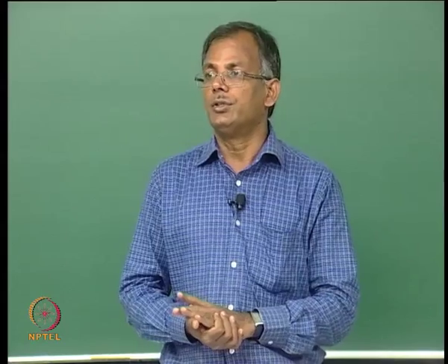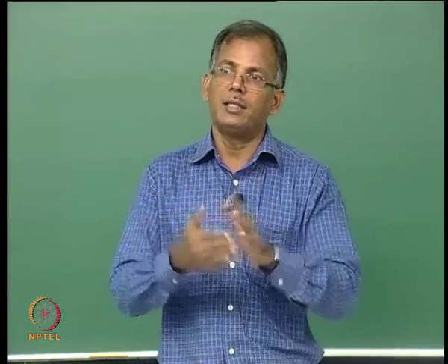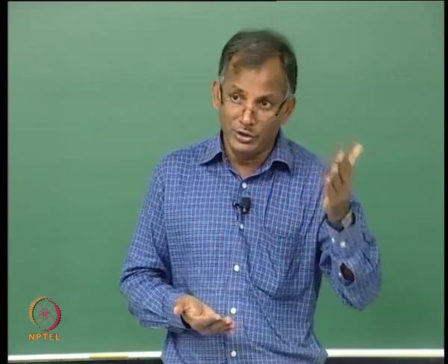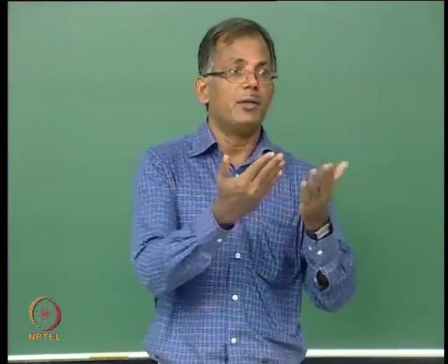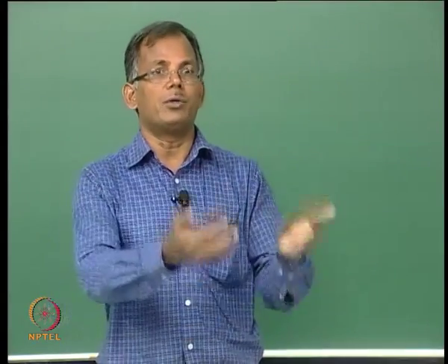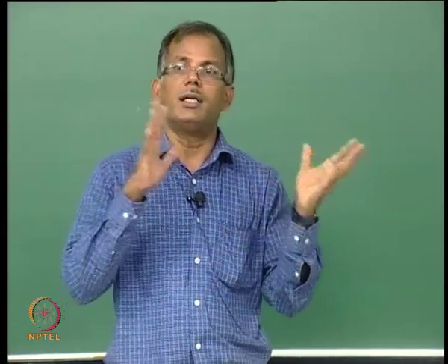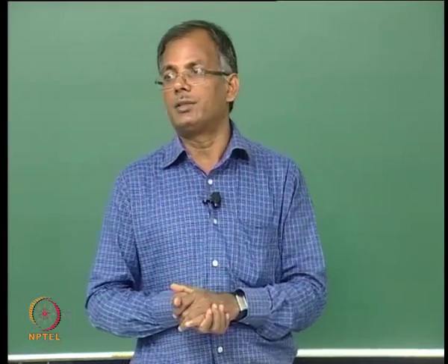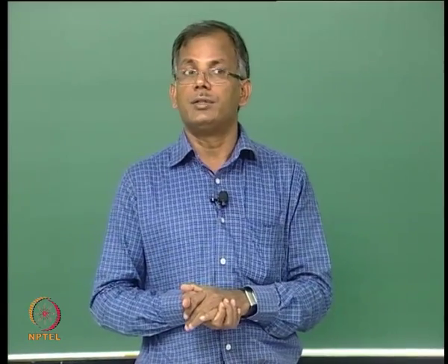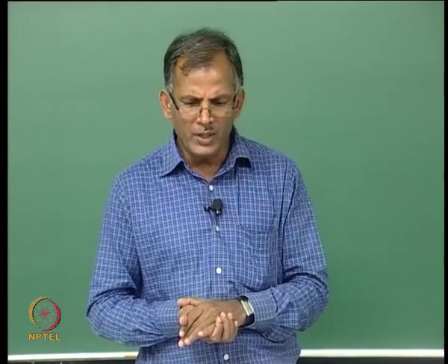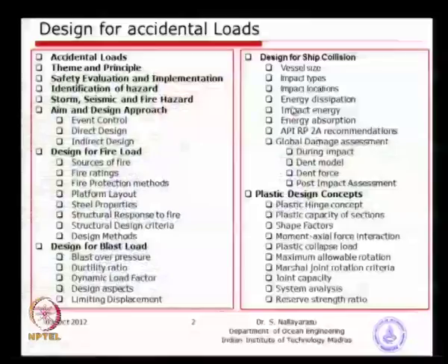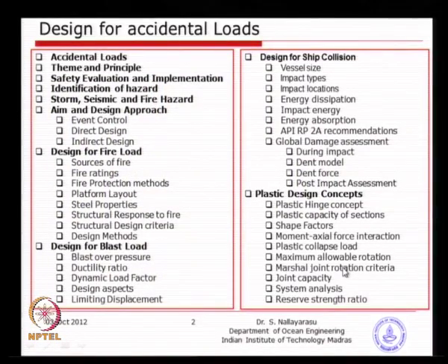So, those things may happen, and in those cases the structure may get damaged, and you may have to repair it in the future to bring it back to service, but it is not necessary that it should collapse. So, you need to have redundancy in the system, so that the structure has sufficient reserve strength that it is not collapsing immediately. While doing all of this, we will see that we are not going to design based on allowable stress, limiting our stresses to a fraction of yield. We are going to go beyond.